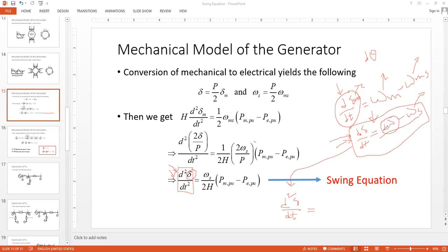What is omega? Constant or a variable? If everything is constant, then there will be no meaning in life. It is a variable. Remember, omega m is the actual rotary speed, and omega is the electrical equivalent of omega m. Omega s is the synchronous speed, which is constant. But omega is not a constant. If both of them were constant, you would never get any deviation here. Omega is a variable which represents the actual rotor angular velocity.